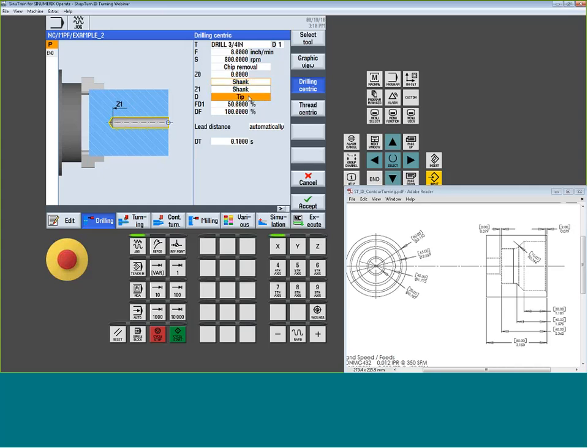So let's say, assume I use tip, but I left the drill depth at the length of the slug. You're going to see it's not going to drill all the way through the shape. And then we can jump over to the other one. You'll see it change. Depth per pass. So here we're going to take a 3/8 first peck depth, and then we're going to back that up by something, and we'll see what the something is in a second.